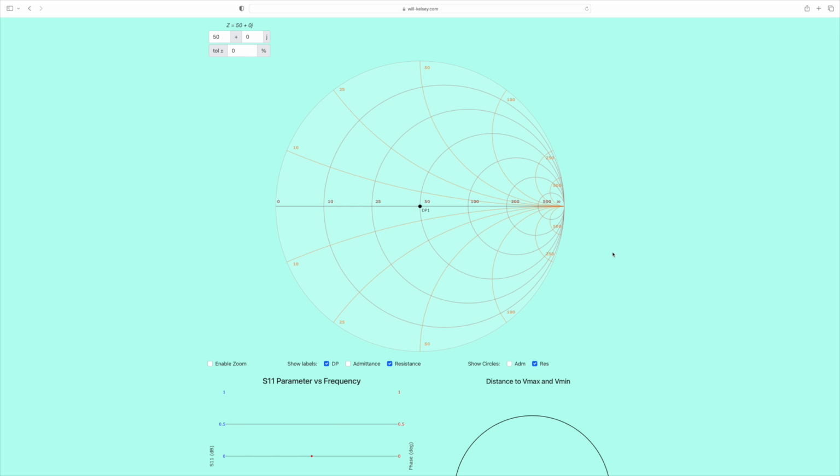But there is another way of looking at exactly the same data from the completely opposite perspective. The glass half full perspective, if you like, which is to say, instead of asking what is stopping our signal getting through, which is effectively what impedance is, we could ask how successfully our signal is getting through. How well our signal is achieving the goal of making it through the circuit. And this is what is known as admittance.